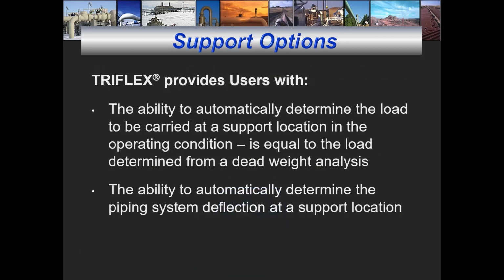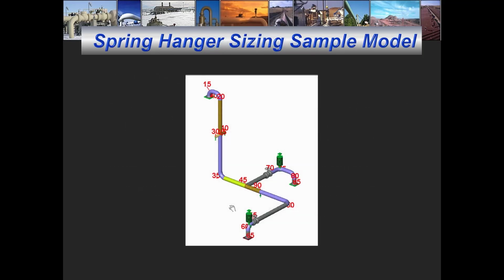So TRIFLEX automatically determines the load to be carried at the support location. It automatically calculates the dead weight loads, and of course deflection and all other loads. This is an example of a spring hanger sample model.